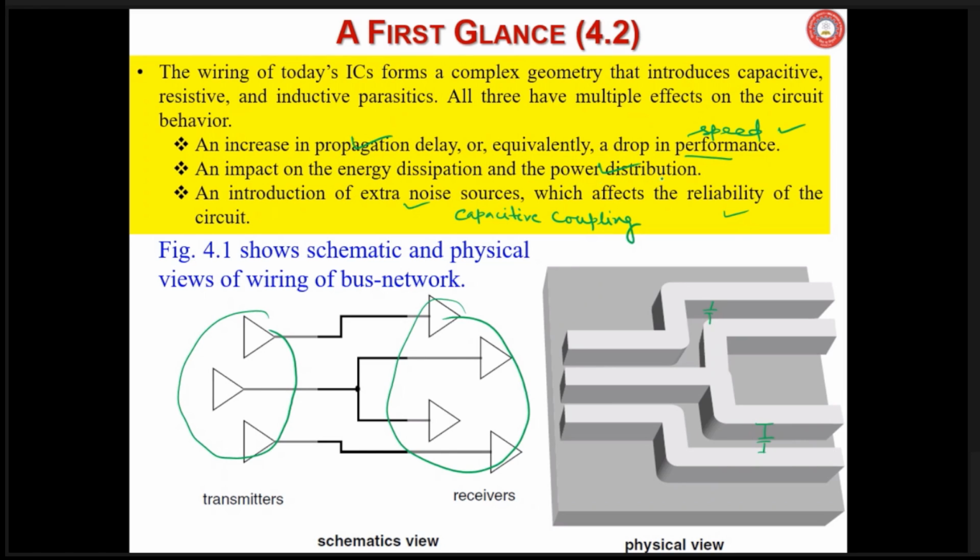And the power distribution. Power lines, also ground and your VDD, will be routed by metal lines only, but those are normally the top metal layers. Say if you have 10 metal layers, possibly the 10th metal layer at the top will be for VDD, ground, and clock signals. Clocks are also routed with wider metal lines, and top layers are wider. Bottom layers are denser, and hence their width, length, and thickness are very small.